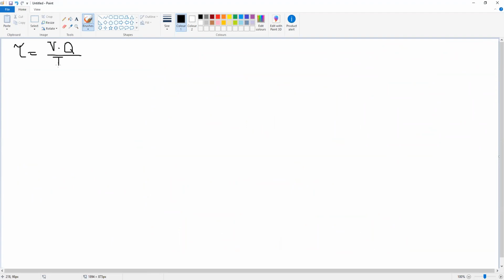So again, tau equals V Q over I T. And we already know V, given 15 kilonewton. I, from the calculation, Ix dash equals 5.207 divided by 10 to the power 6 millimeter to the power 4, and this is the cross section again.